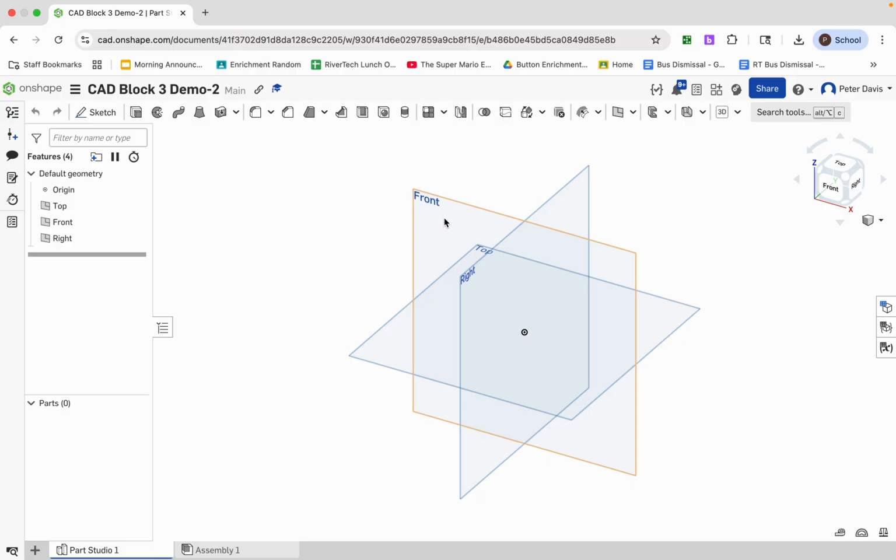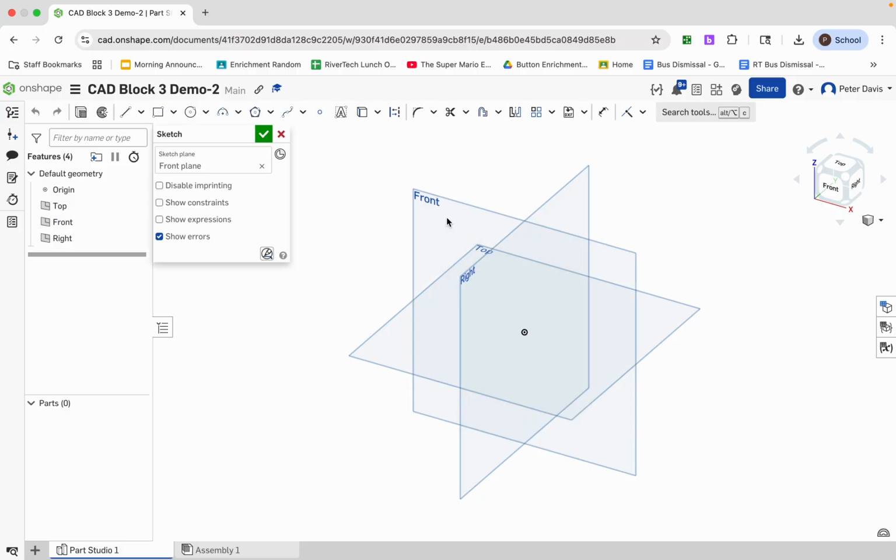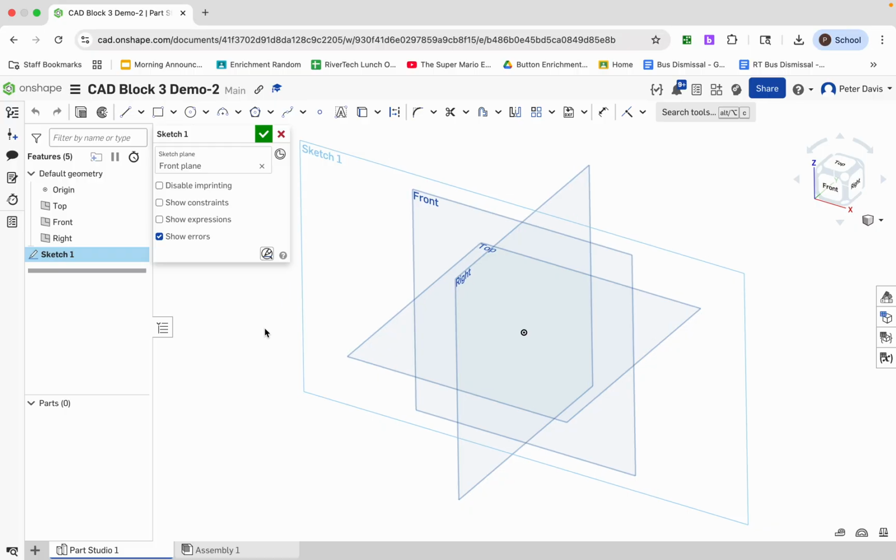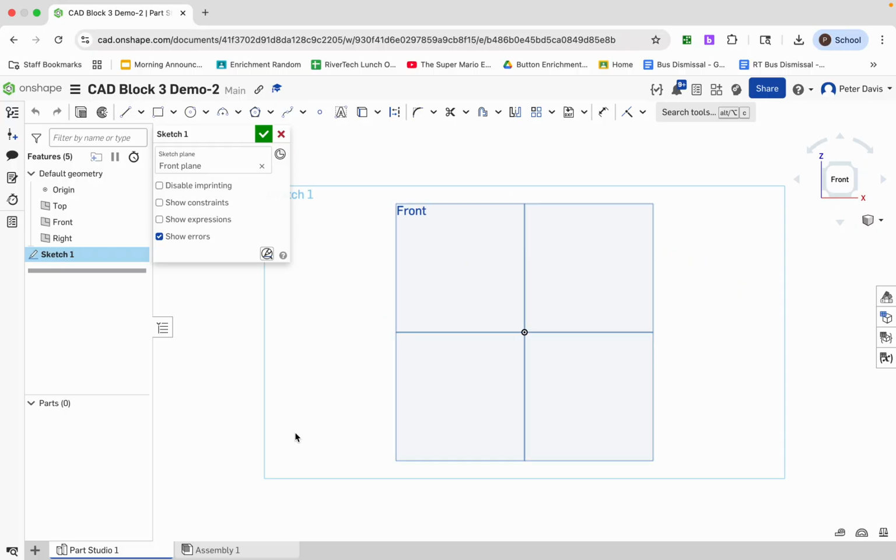So just like before, I'm going to start with my front view. I'm going to create a new sketch. All right. I'm going to go normal to it. If the planes are visual distraction for you, then you can turn them off. In this case, you already know how to do that. So I'm going to leave them on. I'm going to click, drag, drop a point down. And then I'm going to go to my linear sketch pattern, select that point. And just like before, I'm going to give myself a grid of 8 by 8 dots.